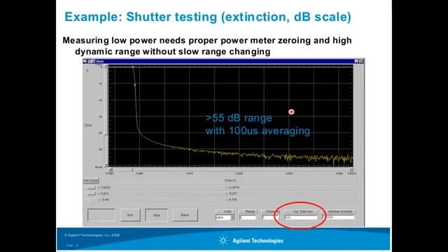well, it's displaying the kind of dynamic range we have when making this measurement. And like we'll show, the dynamic range, of course, depends on the averaging time we use. Shorter averaging times have a higher noise level, so we would have a hard time measuring down at this low power level. Another thing that's important is establishing the 0 power level in that case. And so for making this kind of measurement, it's important to use the power meter zeroing. Basically, that's just a case of making sure there's 0 light on the power meter by putting some kind of darkening elements in front of the power meter to block it, turning off the light sources. And it measures the electrical signal still coming from the power meter, and that establishes the 0 level.